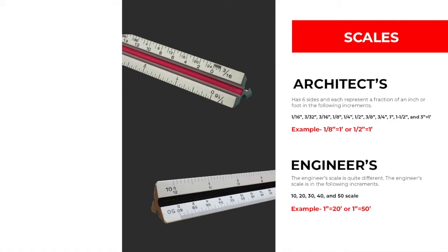In those cases, if I'm reading a drawing or plan that's 1 inch equals 100 feet, I'm going to be using the 10 portion of the engineering scale and simply in my mind adding an additional 0 to the scale so that 1 inch would represent 100 feet. So I'm doing a little bit of math in my head in order for this to actually work for a drawing that might be at 1 inch equals 100 feet. 1 inch would mean 100 feet. I would add in my mind one additional zero here, but I'm actually adding two zeros here.